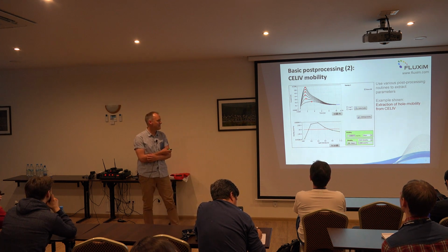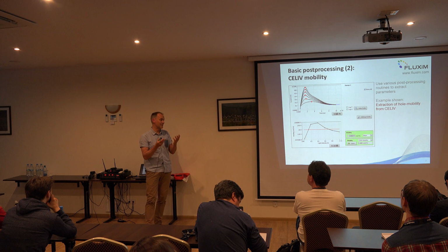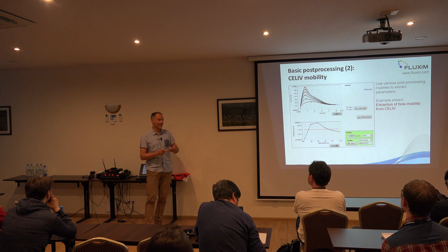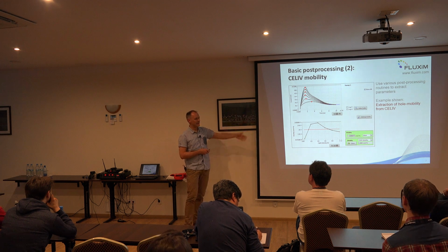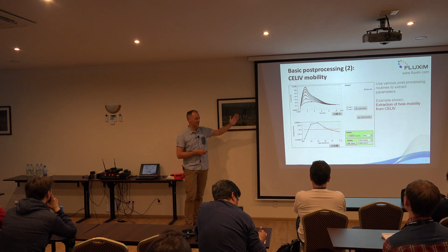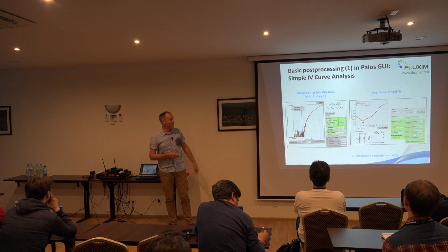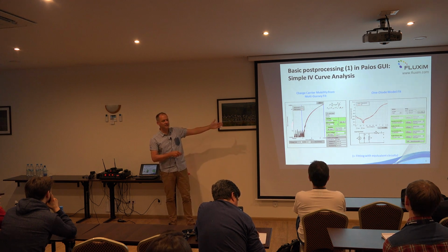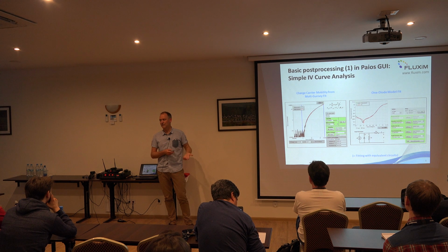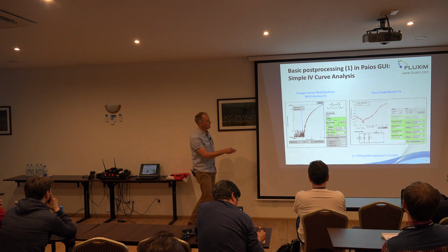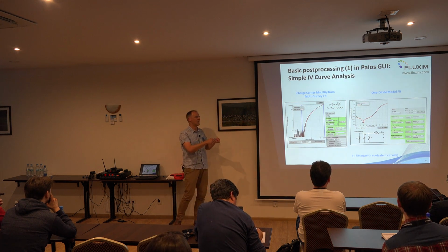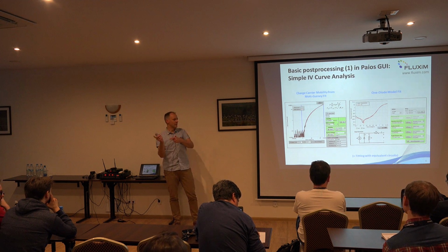Yeah, it's indeed, as you know, in the physical model you need electron mobility and hole mobility. And in some of these experiments you don't even know for sure whether you see the majority carrier now, electrons or holes. So it's really not so clear. But let's say if this here is a PIP device, a hole-only device, where the IV curve is probably dominated by holes, then you could assign this mobility to the holes and then use the same hole mobility value in the drift diffusion model afterwards.